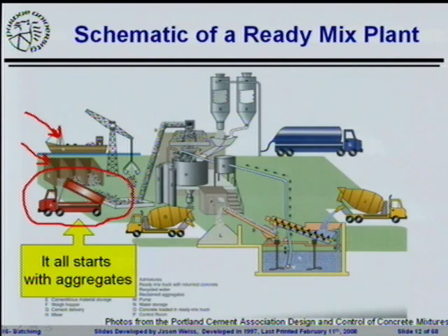There's going to be more risk because you may or may not get the aggregates that you think you're going to get. So you have to have a different quality control procedure. The moisture content of the aggregates can change, which is going to depend a lot. And there's also a whole risk associated with whether there is enough aggregate to even keep the plant running. What happens if there's a traffic jam today? There's another little risk that happens, especially when you get a lot of new drivers coming in, and especially where the drivers are delivering their own materials.